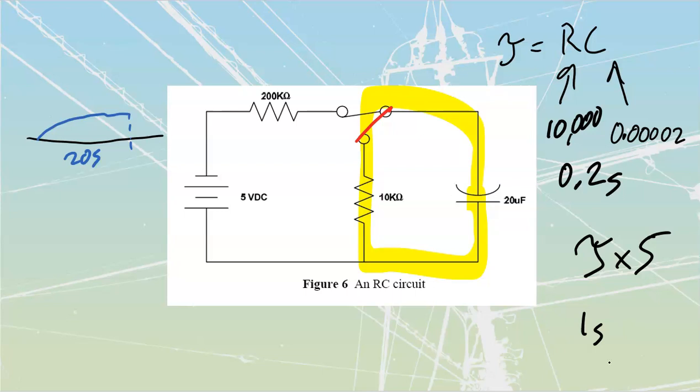This means that if I were to graph this, my discharge curve is going to look like this. It's going to be so rapid that it's almost going to appear to be instant. Like that, and then we would go and have another charge over the next 20 seconds, and another really quick drop. It would form a really, really good sawtooth type of voltage that we could utilize.